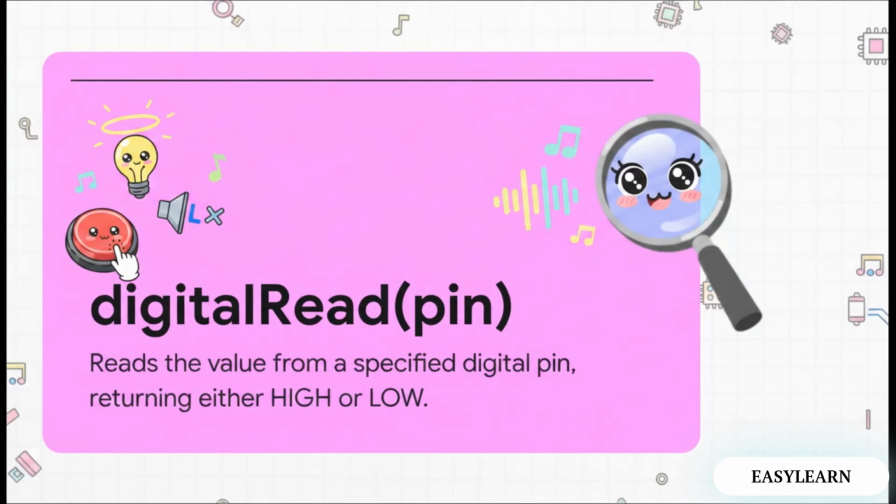And you guessed it, if digitalWrite is for talking, then digitalRead is for listening. The Arduino uses this command to check the state of a pin. It's basically asking, hey, pin 2, is your voltage high or low right now? And that's exactly how you'd find out if a button connected to it is being pressed.